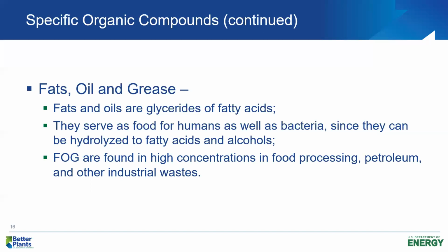So oil and grease can create problems in the sewer system, and oil and grease can create problems at the treatment plant. Animal vegetable oil and grease is very biodegradable in our bodies and by bacteria if it's widely dispersed in the wastewater, and so it can exert an oxygen demand.